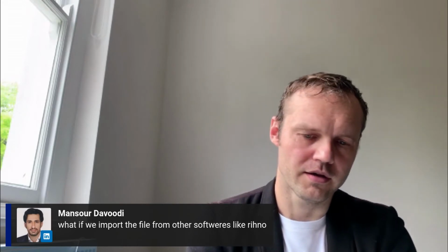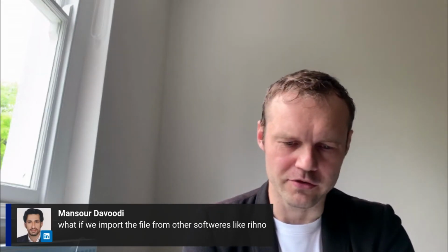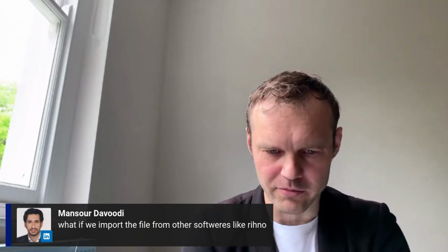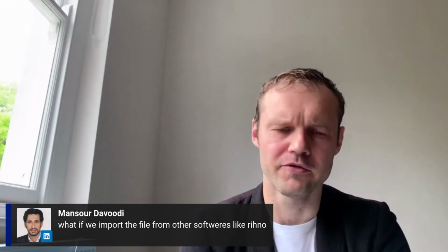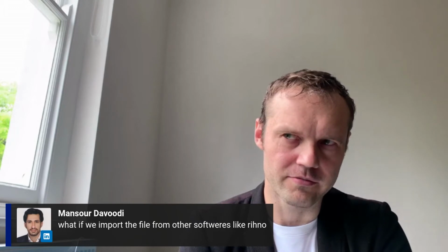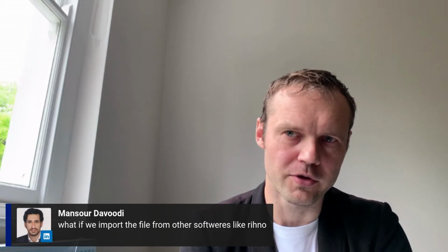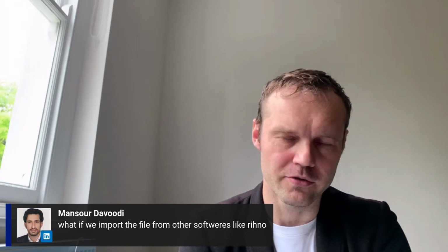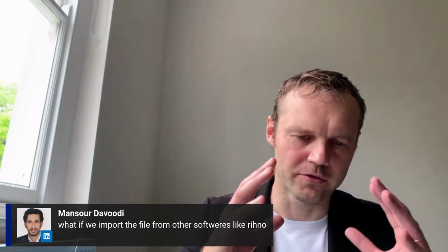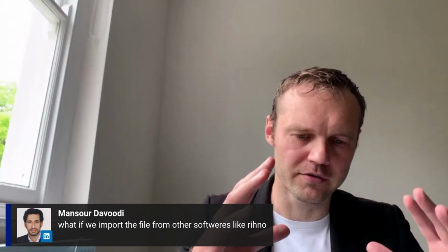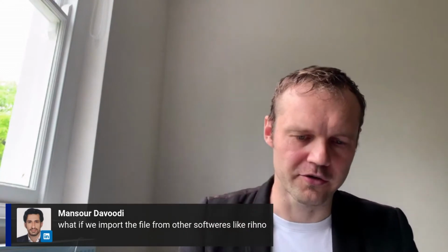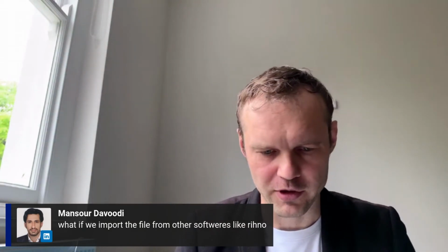Thomas? Yeah, Rhino has also introduced a subdivision platform just now. I haven't had that much time to do anything with it. I think it's good, but if you want to import a Rhino subdivision model, you need to save it as OBJ, but you cannot have any smoothing on it. You need to have hard edge subdivision, and then just export it as OBJ, and I think it will work. Okay, thanks for that one.